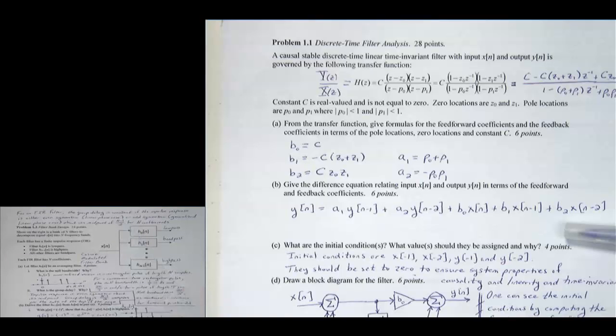And we've derived this a couple of times for the 2-tap averaging filter and the first order difference. We always pulled out the phase shift equal to the midpoint in time. From there, we found that we got a linear phase times an amplitude function. We did this in lecture 5, slides 17 and 18.